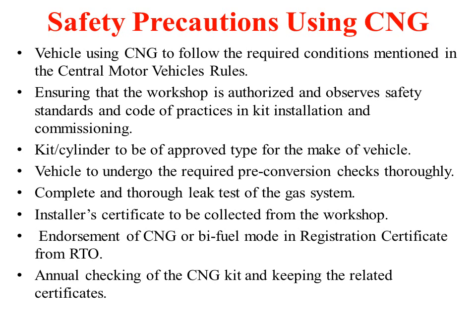They should get the installer certificate from the workshop. And of course, whenever a CNG kit has been fitted to a vehicle, or in a biofuel mode, it has to be entered in the RTO. They should get the registration certificate from the RTO, and annual checking of the CNG kit has to be done and the latest record kept. So that means every year they should get the annual checking, making sure that it is working safely.